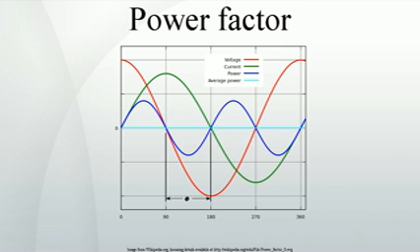This apparent power must be produced and transmitted to the load in the conventional fashion, and is subject to the usual distributed losses in the production and transmission processes. Electrical loads consuming alternating current power consume both real power and reactive power. The vector sum of real and reactive power is the apparent power. The presence of reactive power causes the real power to be less than the apparent power, and so, the electric load has a power factor of less than 1.